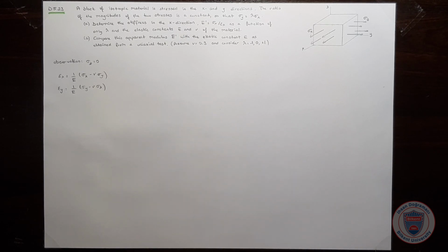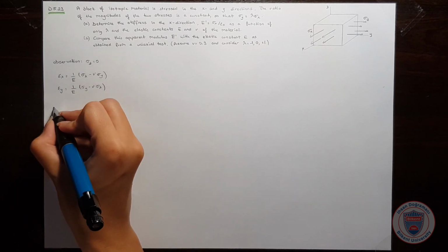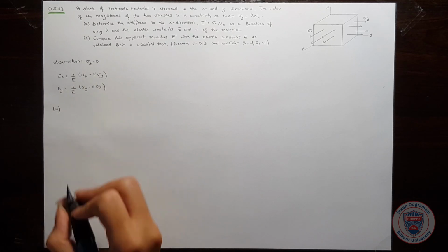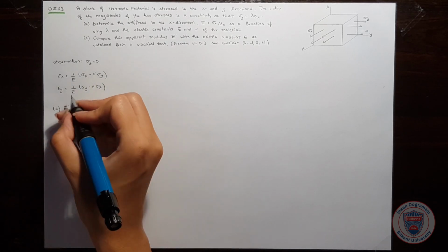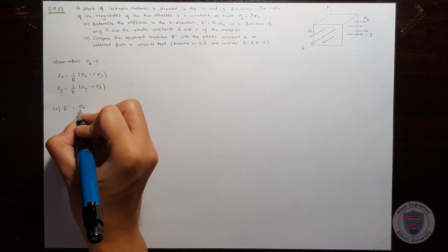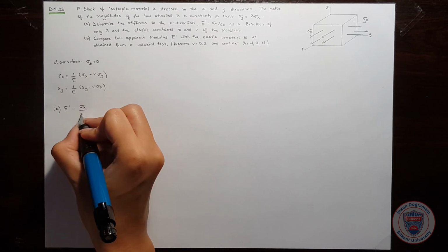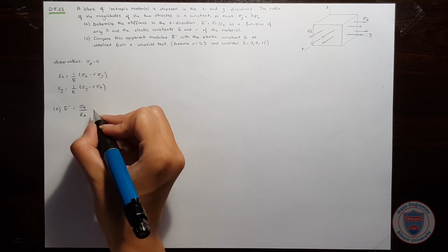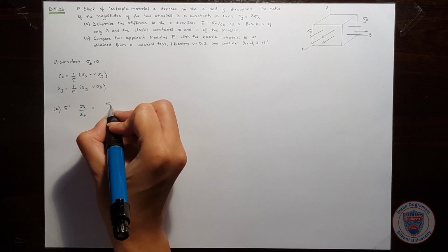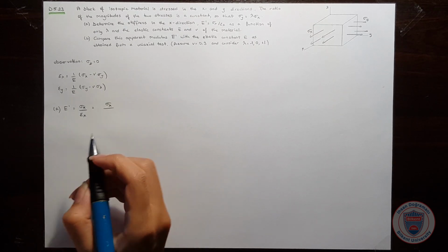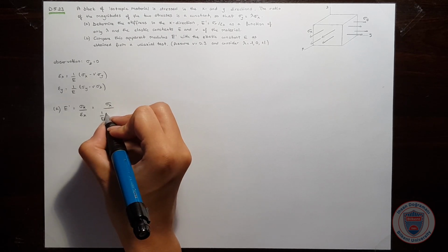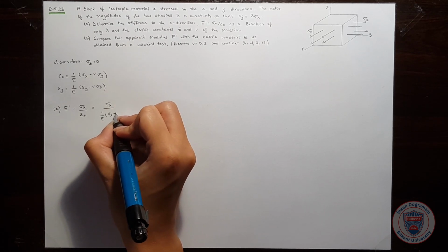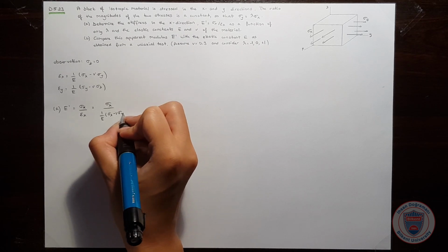Let's start with part A. We know that stiffness in the x direction is sigma x over epsilon x. And we can write epsilon x as 1 over E times sigma x minus Poisson's ratio sigma y.